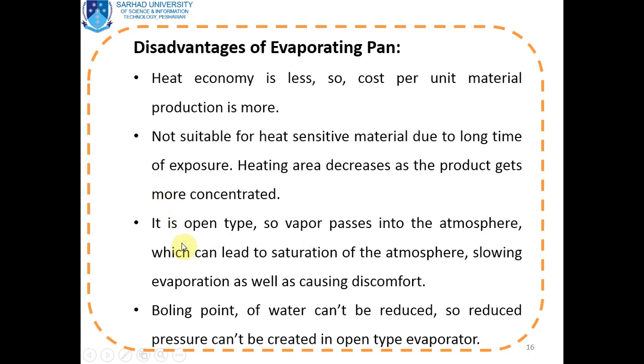The third disadvantage is that it is an open type of equipment, because we have to put the material which is to be concentrated, and so vapor passes into the atmosphere, which can lead to saturation of the atmosphere. I have told you that proper ventilation of the room should be done, otherwise the vapors will circulate in the room, slowing evaporation as well as causing discomfort in the atmosphere.